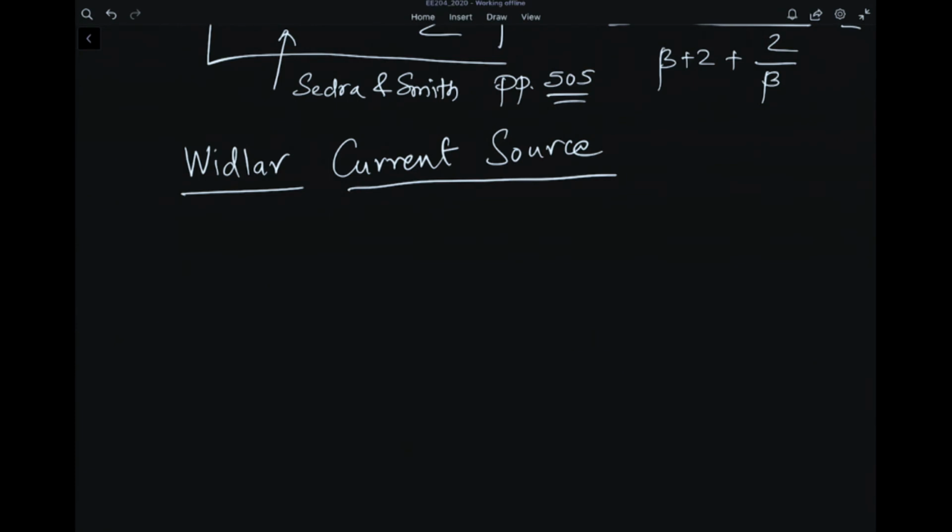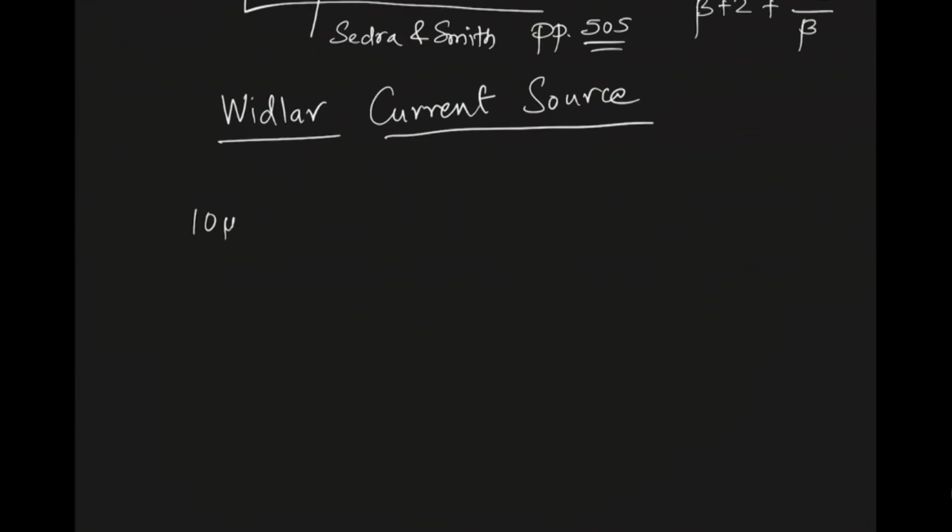The next current mirror I'm going to tell you about was invented by Bob Widlar, and it's called the Widlar current source. One of the issues that you have in bipolar based designs, imagine you don't have any MOSFETs. So this is coming from the pre-MOSFET era, and you wanted to develop a really small current. Let's say you needed a 1 microamp or 10 microamp current. Then it was a little bit hard at that time because supply voltages were high, and along with that, so let's say that I wanted to develop a 10 microamp current source.